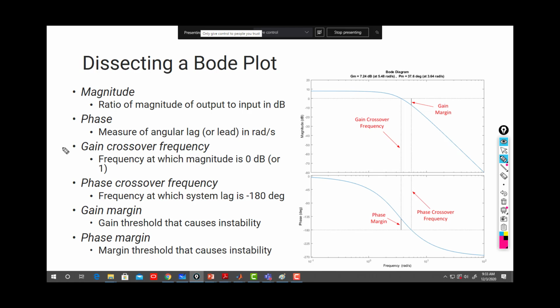That's why we focus in frequency analysis on Bode plot representation. So we have four main characteristics, as we have characteristics for time domain: settling time, overshoot, etc. So one is the gain crossover frequency, and how we define the gain crossover frequency is the frequency at the gain of 0 decibel.